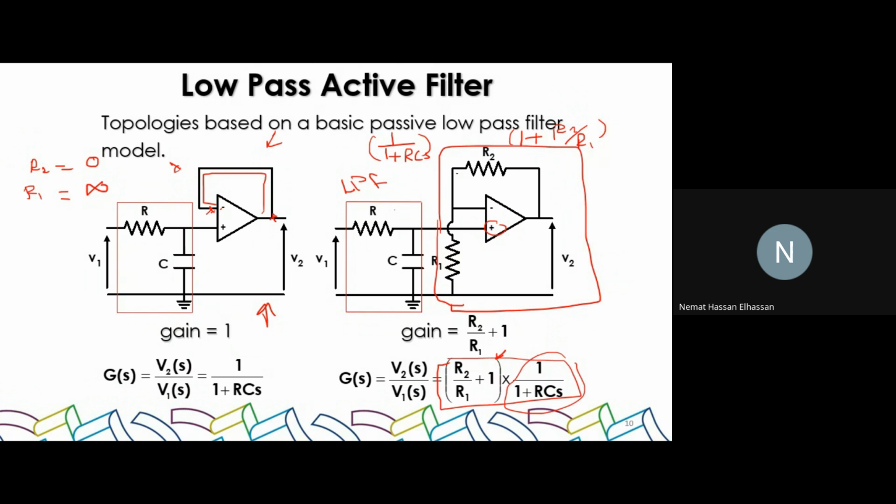So if I want to get the gain of this non-inverting amplifier, it's 1 plus 0 over infinity, right? And 0 over infinity is what? 0, right? So the gain is equal to 1. This is called a voltage follower. Whatever is at the input, the gain is 1. Input is 2, the output is 2. The input is 3, the output is 3. The gain is 1. We only multiply by 1. We call this type of circuit the voltage follower. Is it clear?